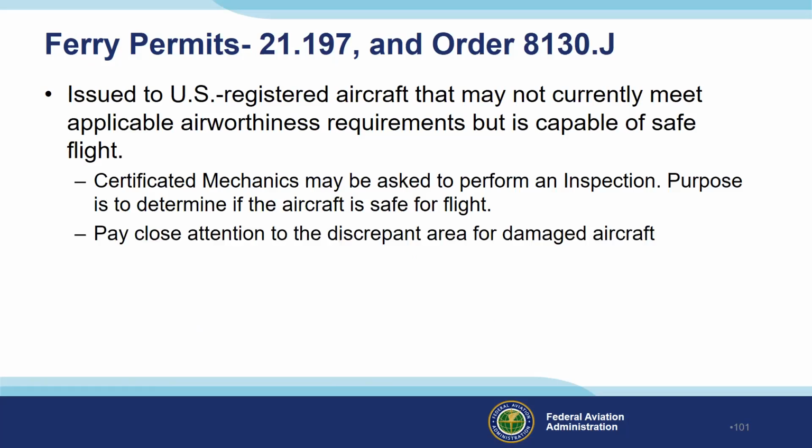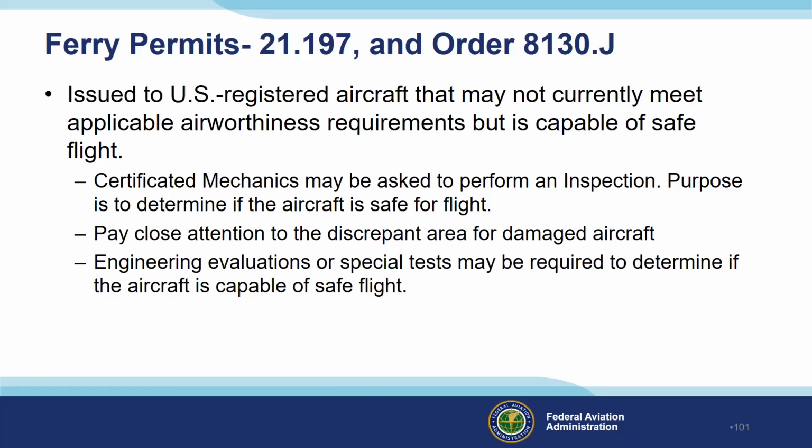Make sure you pay close attention to the discrepant area for damaged aircraft. And keep in mind that an engineering evaluation or special test may be required to determine that the aircraft is capable of safe flight. You may not be able to tell using your own expertise or knowledge or equipment.